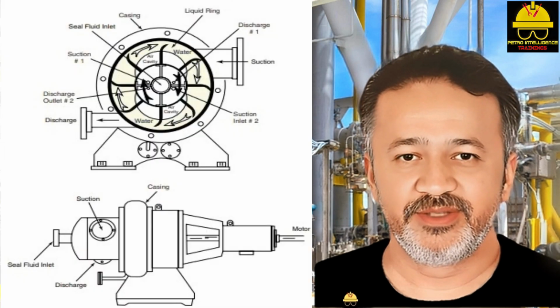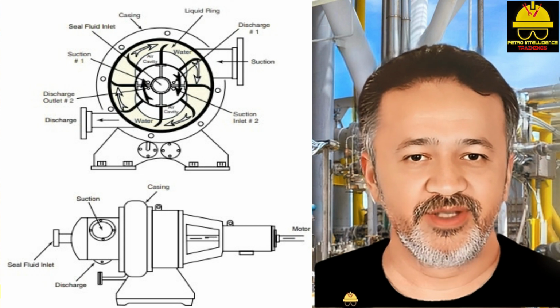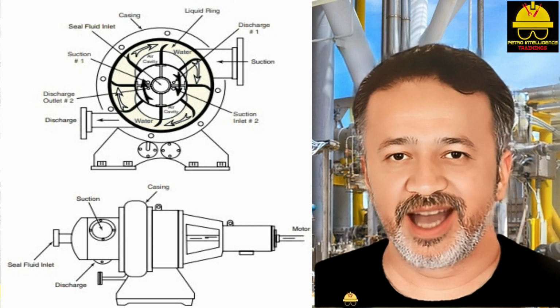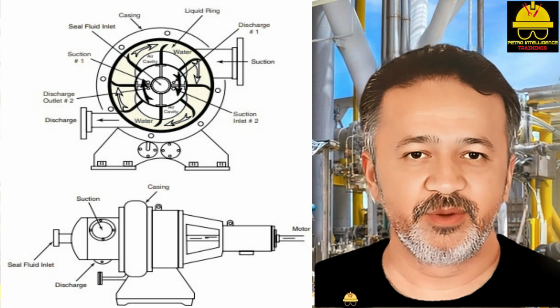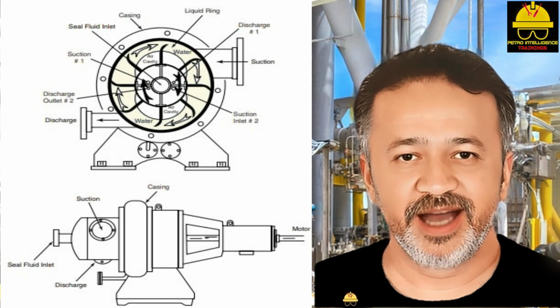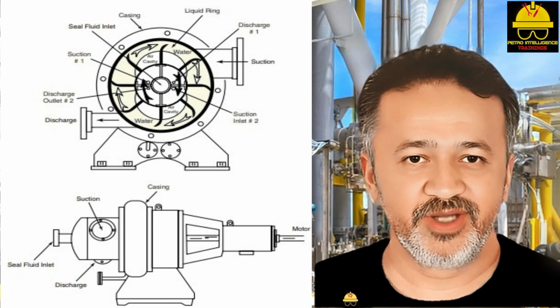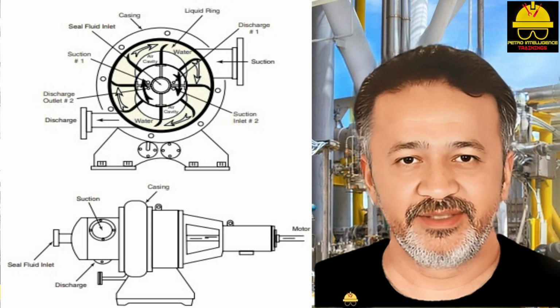As the rotor turns, the fluid is centrifugally forced to the outer wall of the elliptical casing. An air pocket is formed in the center of the casing. As the liquid ring compressor rotates, a small percentage of the liquid escapes out the discharge port. Makeup water or seal liquid is admitted into the compressor during operation. The liquid medium helps cool the compressed gases.